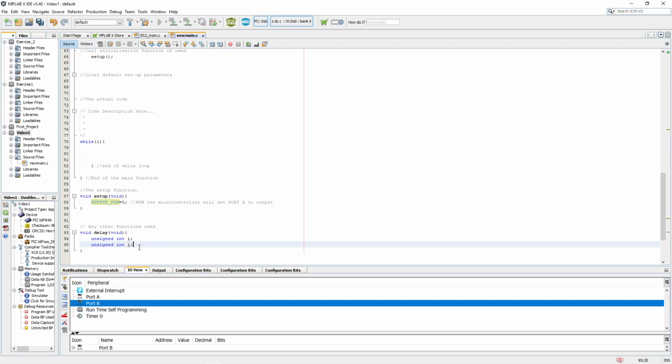So what you do is use that 1 megahertz of frequency and manipulate it in such a way that it takes time to do all the calculations, and that way you create delay, because microcontrollers can seriously be slowed down if you do a loop inside a loop. I'll show you. You do the for in C language: for, L equal to 0, semicolon, L less than 50, semicolon, L plus plus, which adds 1.